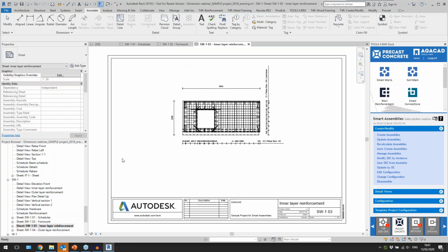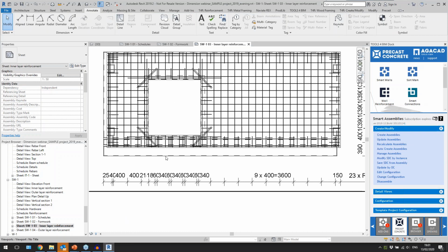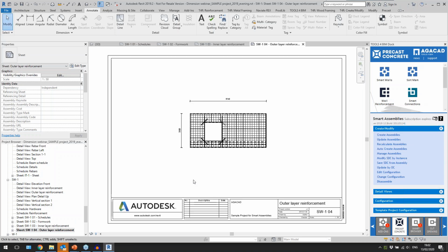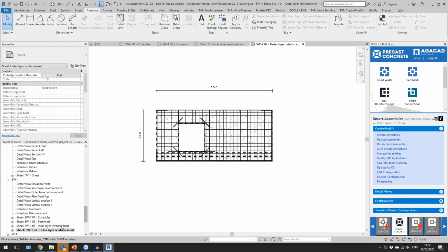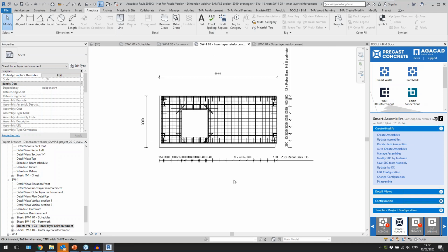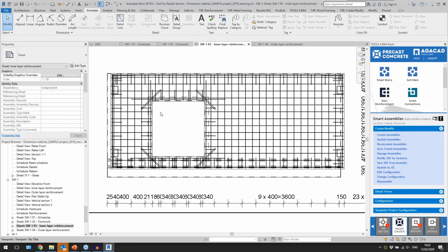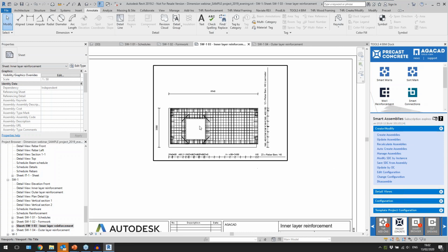And I also see internal reinforcement only, because I have created reinforcement with the wall reinforcement tool, which has assigned partitions, and I can use that as a filter. Only internal, and this one is only external. I didn't get dimensions here, not sure why, but here these are internal reinforcement, and I can work with them,